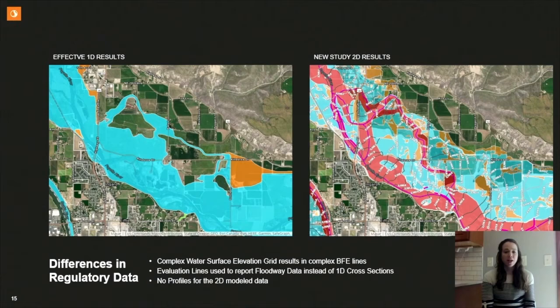In contrast, base flood elevation contours are used in the 2D model. The BFE contours tend to make the maps look more busy, requiring more judgment to determine which contours should be mapped, attempting to capture the detail generated in the 2D analysis, but also keep the maps readable.